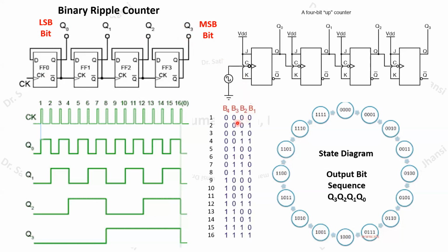So that you can also observe from this, because when you are writing this 4-bit binary, if you make all the combinations, you will find that this is our LSB bit, and at every clock pulse you will find that there is a transition for your LSB bit, 0 1 0 1. So for each and every clock pulse, whenever the next clock pulse arrives, 1 2 3 4, every time this LSB is making a change. You can see that its output is making a transition.